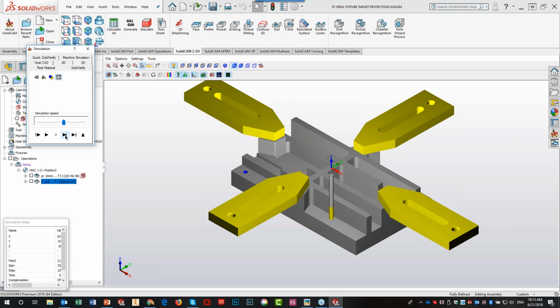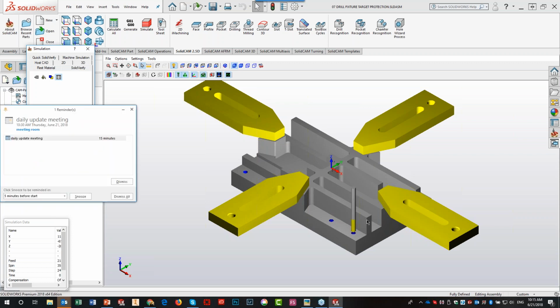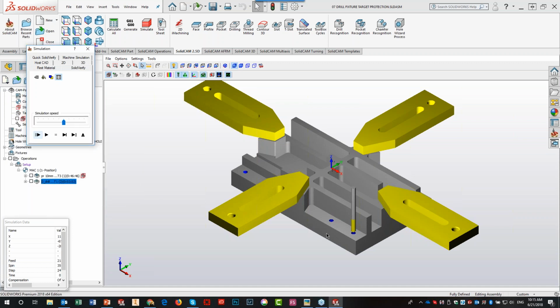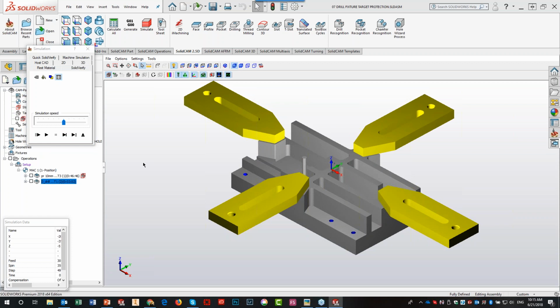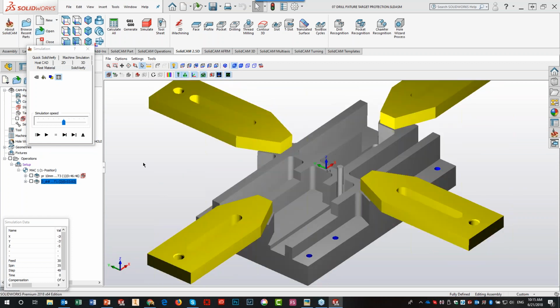Now it's going to go down to that upper surface over there. That's the upper level over there. And again, it's going to go now directly to the next hole. Now, after this hole, you'll note there's a wall over here, and it has to go to this next hole over here. So the shortest distance in this particular case, it's going to jump just above that wall and then go back down. Then go directly to the next hole, again jump over that wall. And let me just turn my part around for a second over here so you can see this a little better.